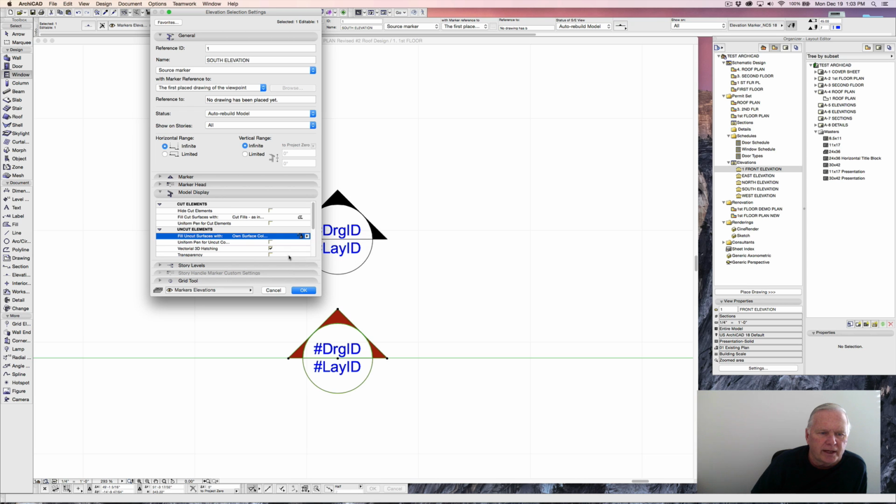So click on that. We're going to leave the Uniform Pen unchecked. Check the vectorial hatching if it isn't on yours, if you're following along. Then down under Sun and Shadows, we're going to click Sun Shadow. On the Mark Distance area, we're going to click Mark Distant Area. We're going to fill with the Own Surface Colors Shaded, vectorial hatching, sun shadow.